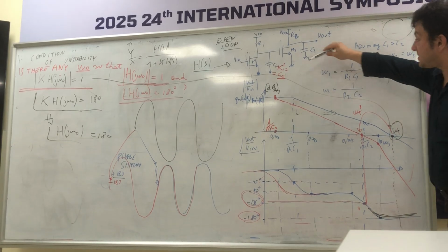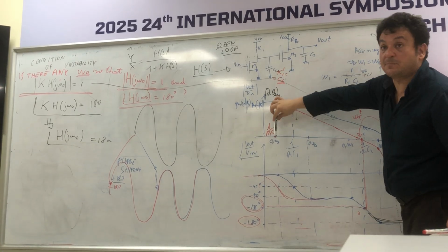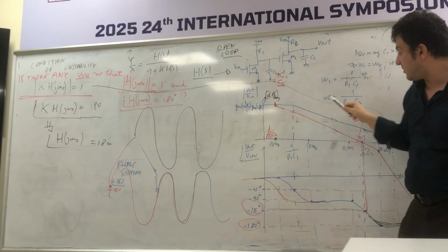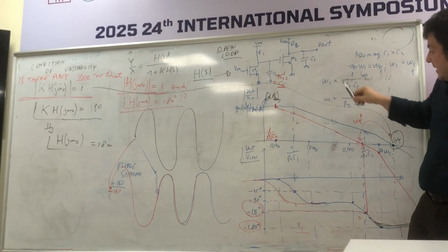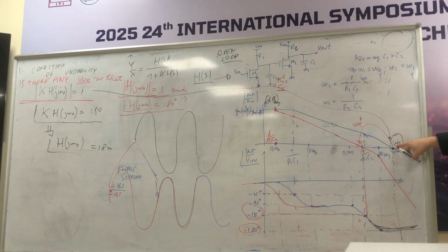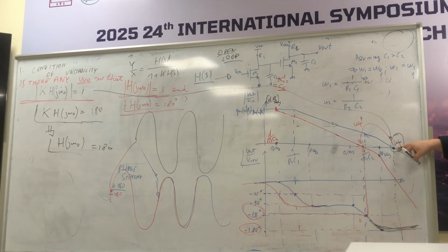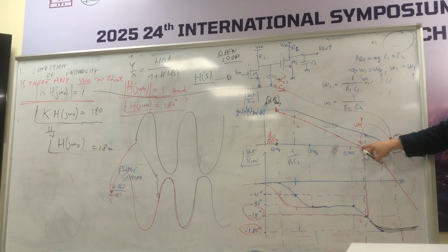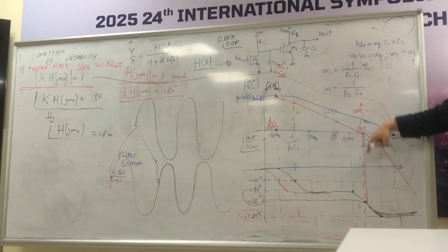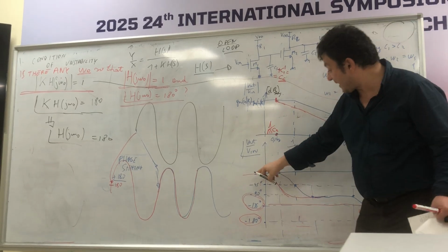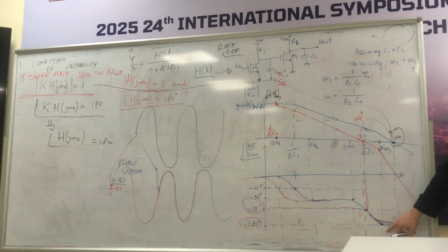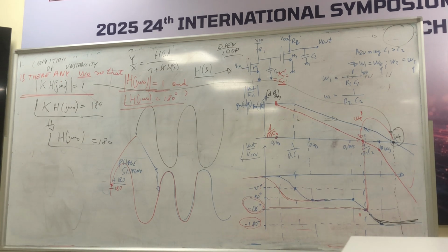So, by reducing the first pole, by increasing the capacitance, what I did, you can check mathematically, just visually, I just reduced the value of the transition frequency, okay, this omega t, so that the respective phase of my transfer function results to be far from 180, okay?